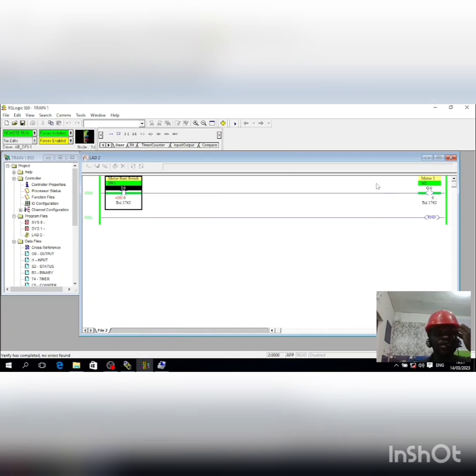Okay, so if you look at the PLC too, on the PLC, it's just indicating that channel 0, output channel 0, is currently energized. Okay, so this is just how to start programming of Micrologix 1200. So we'll stop here for now. Thank you for watching. So to go offline, click here and go offline.